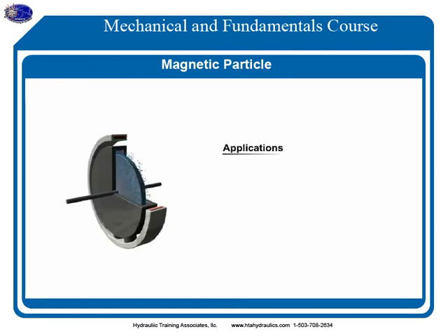Magnetic particle brakes are useful in tensioning and positioning applications in which speeds are continually changing. At zero speed, this type of brake holds well, but in slip conditions it tends to generate considerable heat. Applications would include packaging and printing machinery, conveyors, and factory automation.